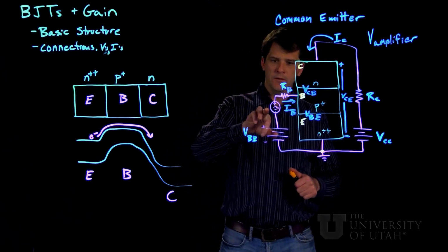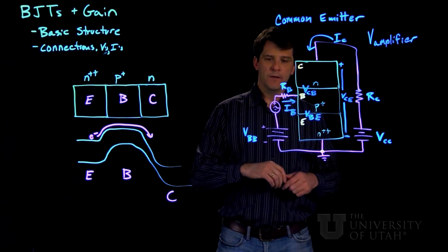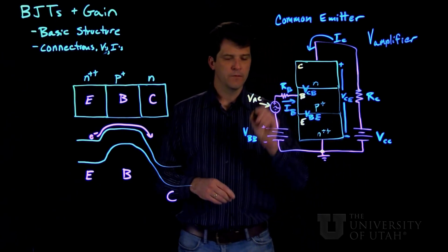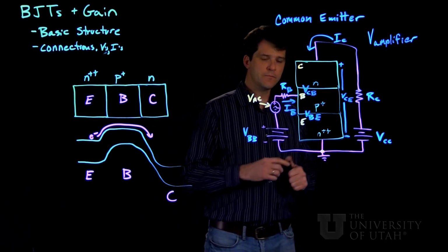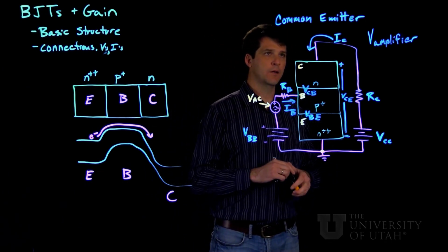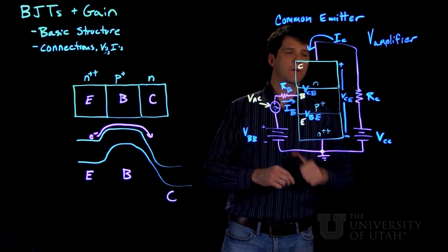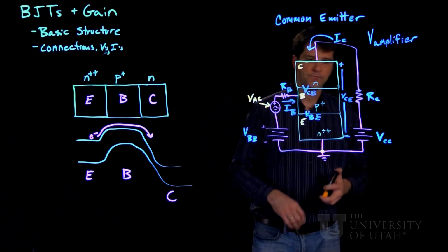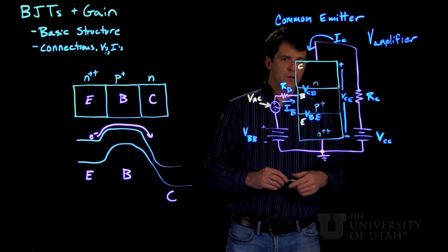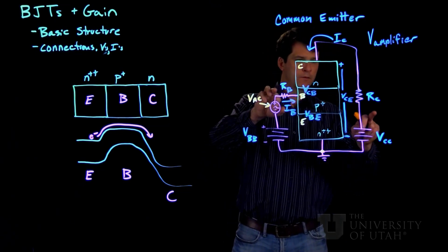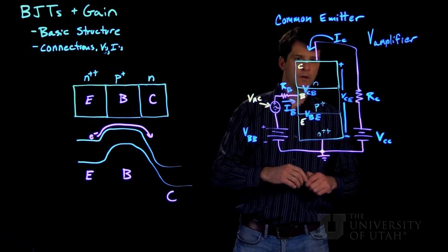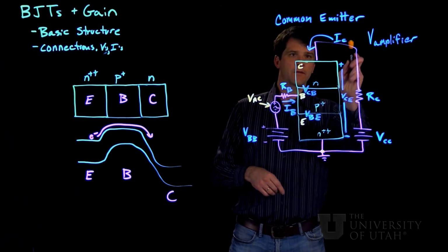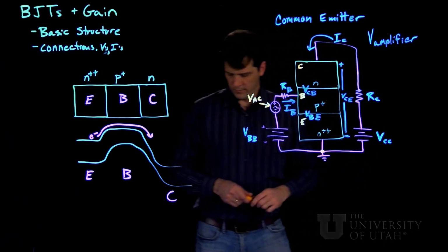So we've also drawn in a little AC source here so that we can add a VAC if we want to do so, and then amplify this signal using the transistor in the functionality of a voltage amplifier. So we need to keep track of these resistances on the base and collector, as well as the currents going into the base and the currents going into the collector here.